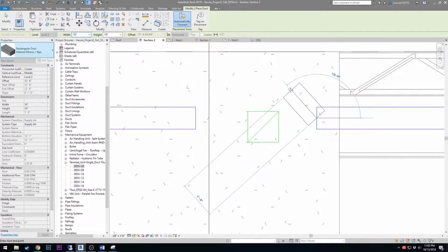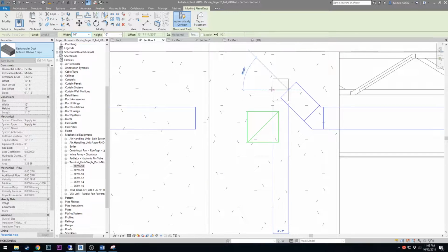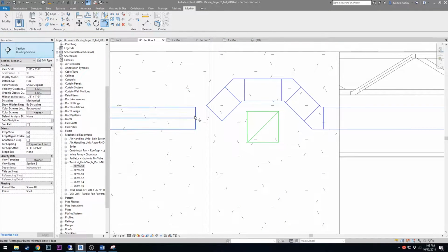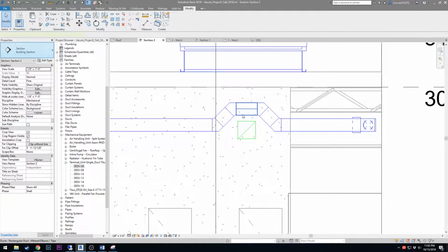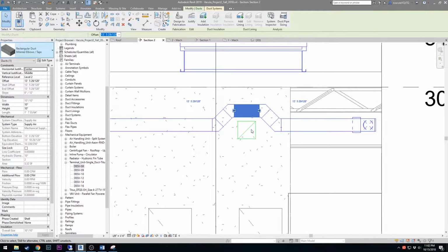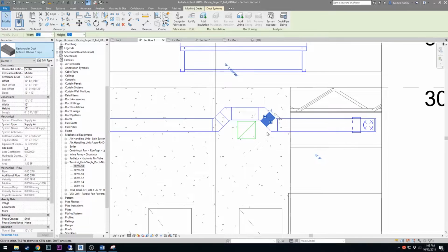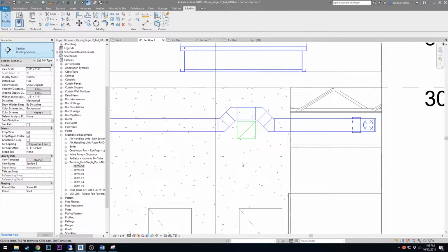So you see that it snaps at 135, that's a 45 degree increment. So we'll draw this duct straight up, horizontal, and down at 45. Now use a trim extend to run these two together. Alright, so that is the transition piece. Make this hop over our exhaust.